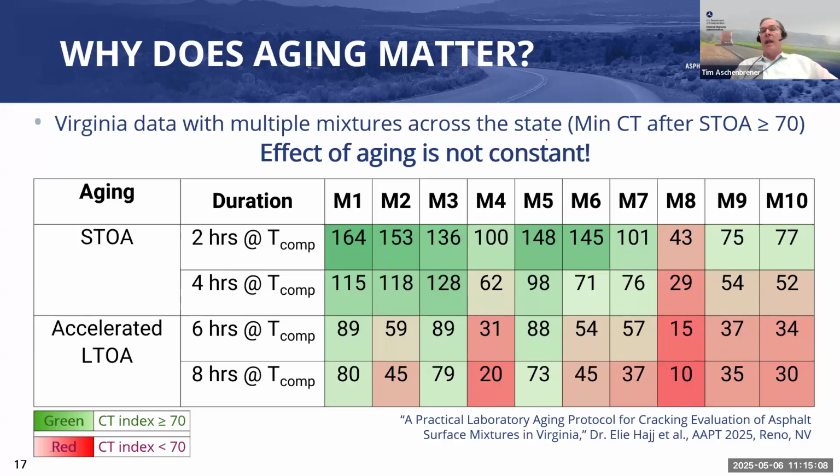And then make sure you're gathering that data as you set up your validation sections to use the appropriate plant mixed and lab compacted, or whatever strategy you have. Because then in hindsight, as this question alludes to, well, I didn't like how the original validation was set up with lab compacted, so now I want to see what field compacted does. Well, then a wrench is now thrown into the cogs unless you set that up initially.